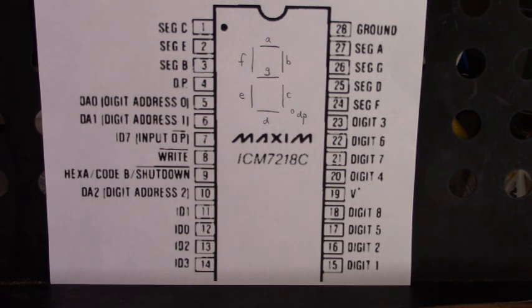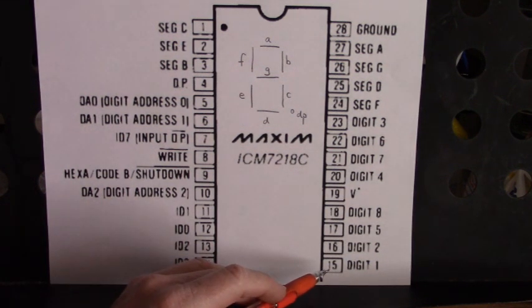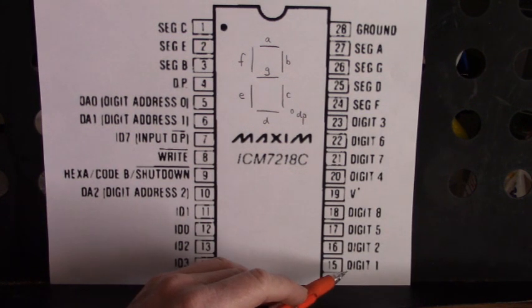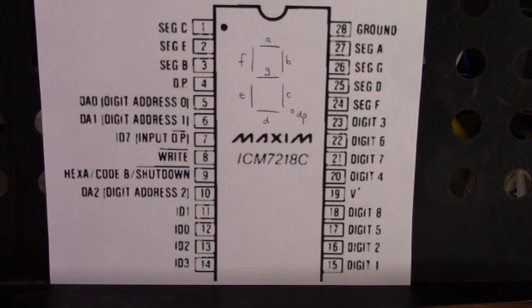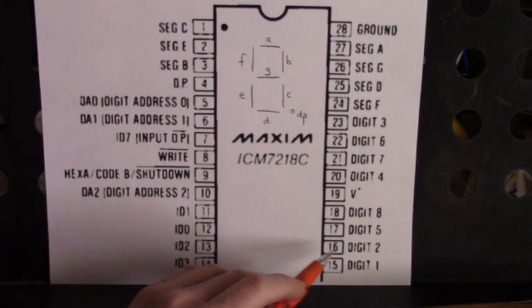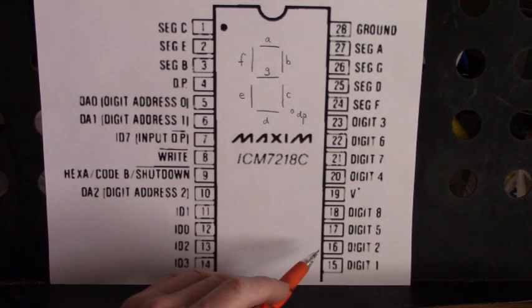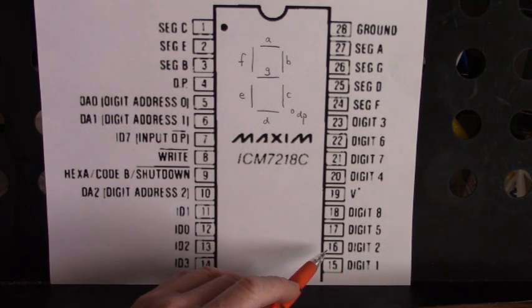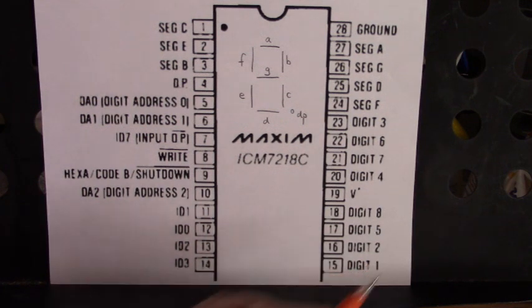And that applies 5 volts to the 7-segment character anode, the common anode input on digit 1. As for instance, if our next value is 0, 0, 1, then this 7-segment display's common anode will be turned on. 16 will go high.